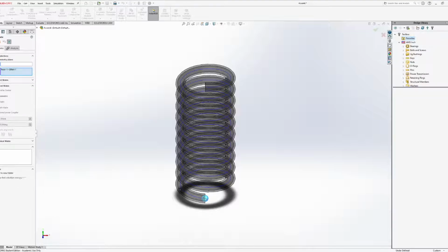So symmetric just means that we need to have some face of an object that is between two other faces, such that that original face is going to be symmetrically between those other faces. We have a width mate, which is similar to the symmetric, only it just needs to specifically be either maybe between two things, but maybe it's centered, maybe it's free to move back and forth, maybe it's a percent of the distance.